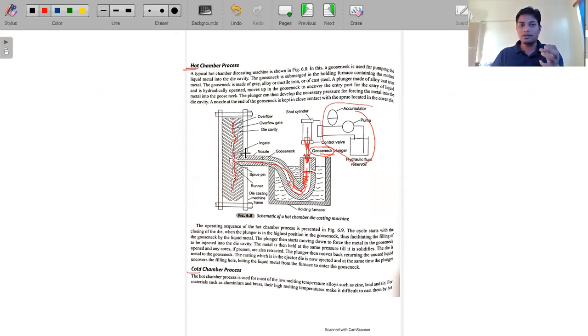So this is the pattern that is left between the movable die and the fixed die. We are filling it inside, and whatever the volume is there, that will be filled. Then we are just keeping it inside, and again this material will be filled. So now this liquid material, because the entry is already provided, will fill inside. But during the solidification it will take some time.